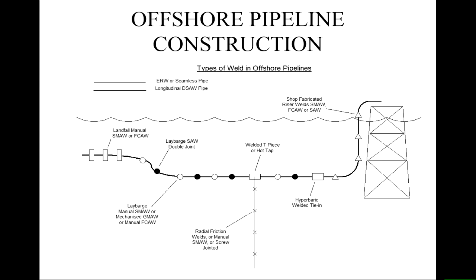If we have to repair things, we will sometimes weld underwater, but we don't weld underwater in the water. We weld underwater in a chamber where the pressure is higher than atmospheric pressure because of the head of water above you. And we call that hyperbaric welding. So hyperbaric welding is not welding underwater, it's welding in a high pressure, which just happens to be underwater in these particular cases.